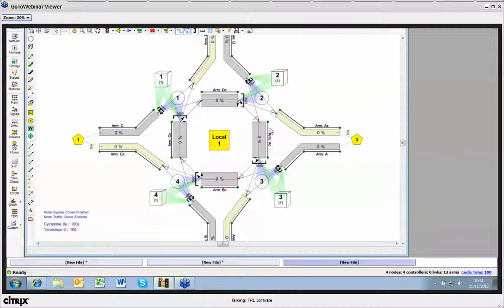The third model is called the CPDM model, which stands for Congested Platoon Dispersion Model. This is designed for flared situations up to sort of 30-ish meters long, where you've got a flared situation at a stop line. That's basically what it's been built for.